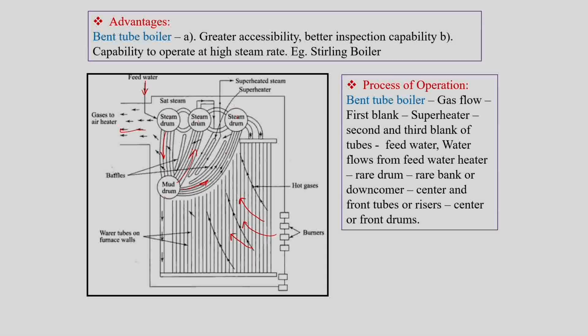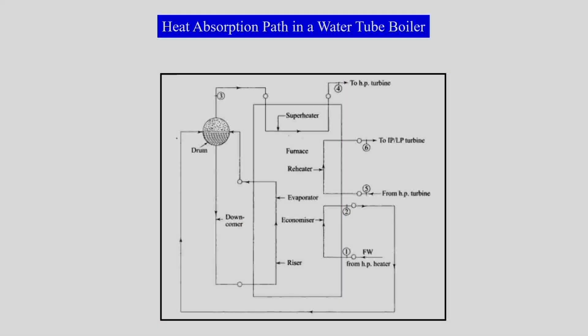These drums are connected with each other so as to have their level similarity, and then they will give the steam of required pressure and temperature to the superheater or to the turbine first. However, intermediate to these evaporator tubes we have superheater tube also placed. In general, at gross, the arrangement of different tubes into the boiler or into the steam generator is like this,